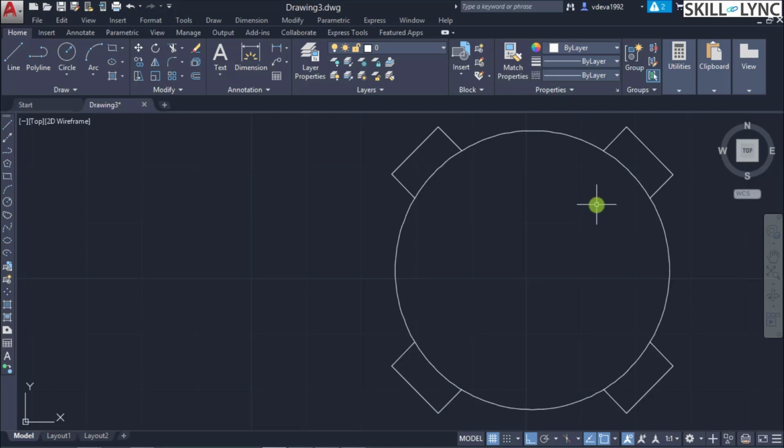One way is you can use the break command again to select the object and go about in anti-clockwise direction to do it, or alternatively you can remove the circle as a whole and then draw an arc between them with the same dimension.